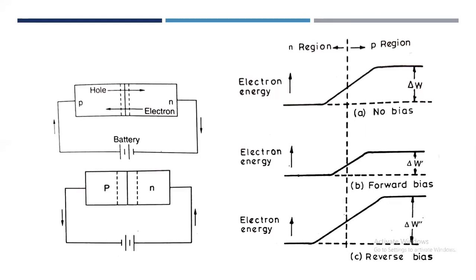Germanium diodes require much less forward bias to conduct. This can be of advantage in low voltage circuits. Germanium diodes have low resistance for forward current, and germanium is a better conductor than silicon. However, the silicon diode is still superior for most applications because of its low cost and lower leakage current at higher temperature. Silicon is mostly used these days.